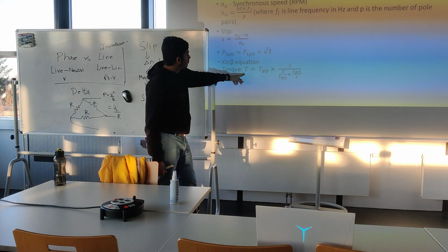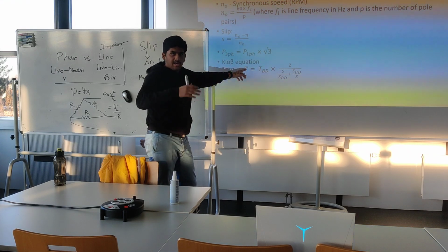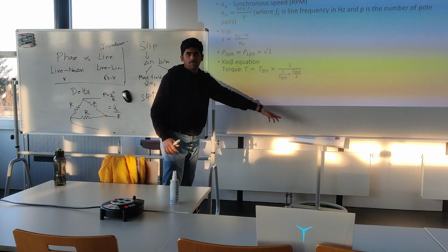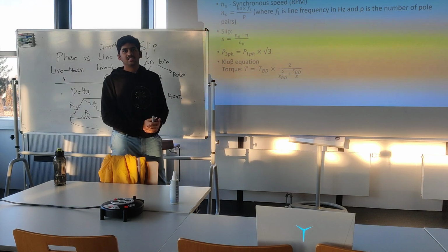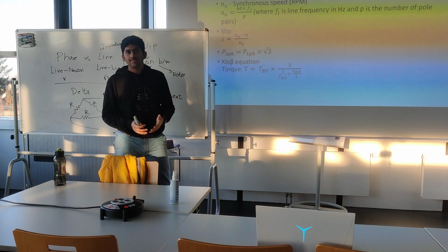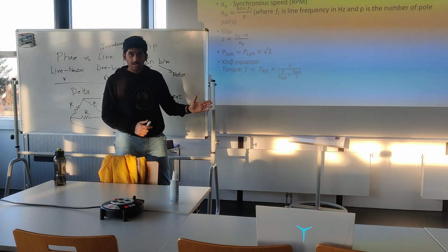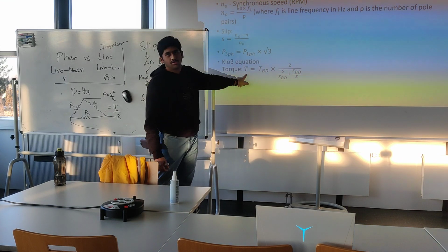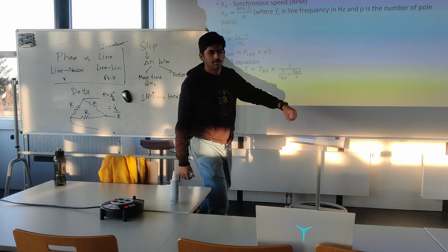It gives the relationship between the torque at any operating point with the breakdown torque and slip. So a very common type of question that we see with asynchronous motors is the operating RPM is given, nominal, the breakdown RPM is given. We use that to get slip and we use that to get the torque. We will do such a question now.